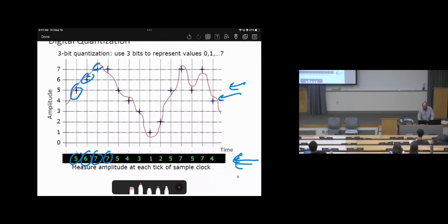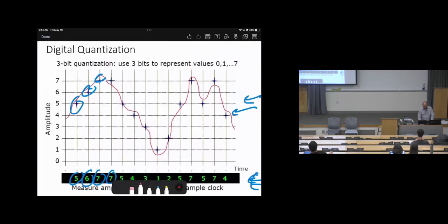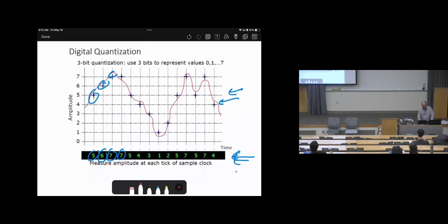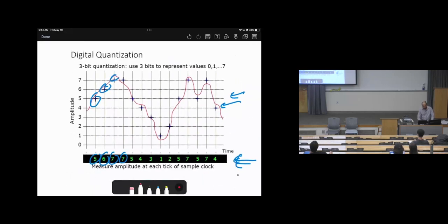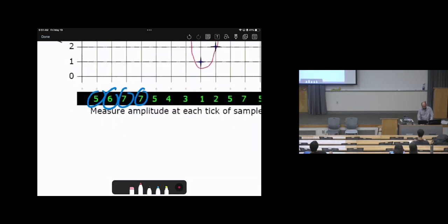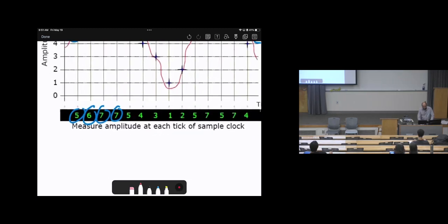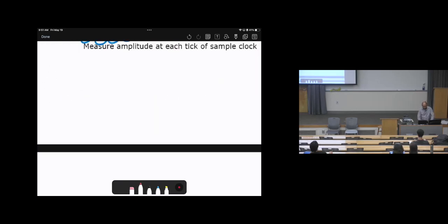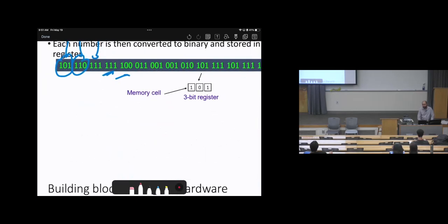We can quantize, for example, this. First, I have an audio. The microphone will convert this audio to an electrical signal. This is, for example, a sample of the electrical signal. Then it will be quantized as shown here, so it will be stored as numbers instead of this graph. These numbers will be stored in binary so the computer can understand it. Then it will be stored as zeros and ones as shown here. Then the digital circuit will come after this step.